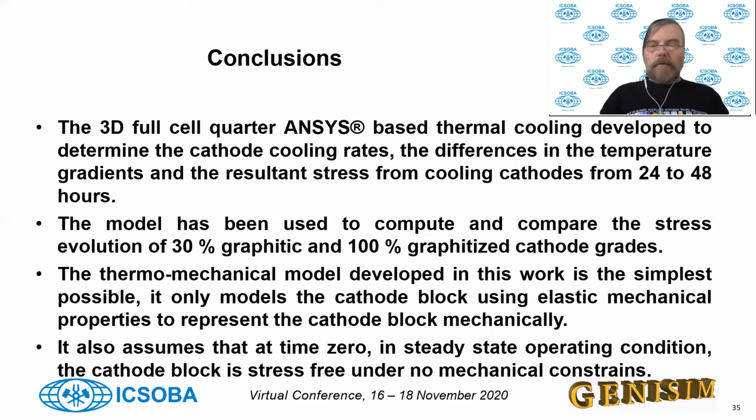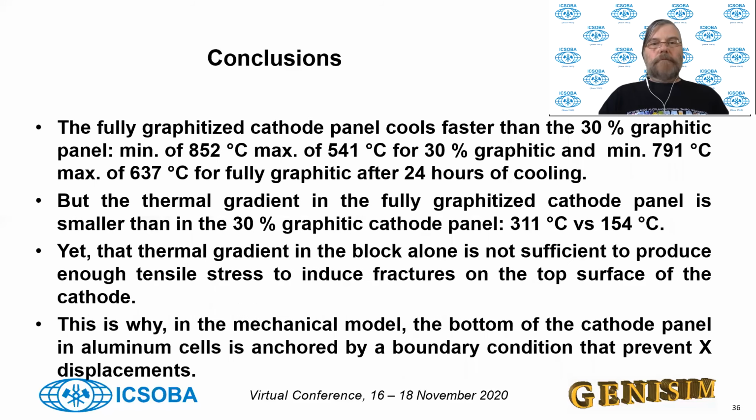So the assumption is that the collector bar will prevent any displacement of the bottom part of the cathode. We are predicting different rates of cooling down for 30% graphitic and graphitized, and different intensity of thermal gradient. But since they are both subject to the same restriction of displacement, the same type of stress occurs in both types of grade.